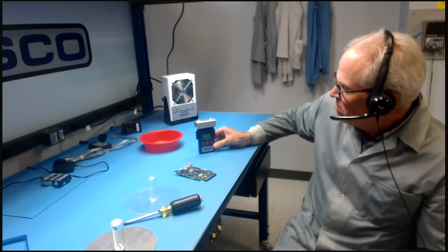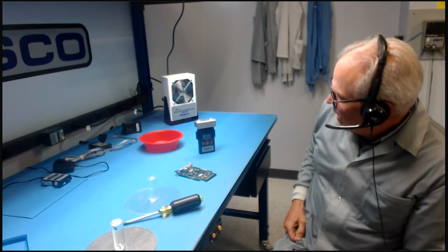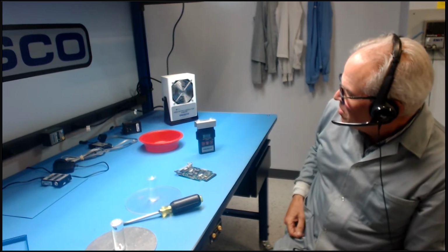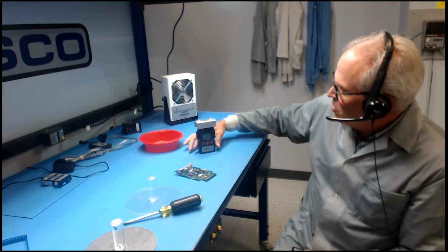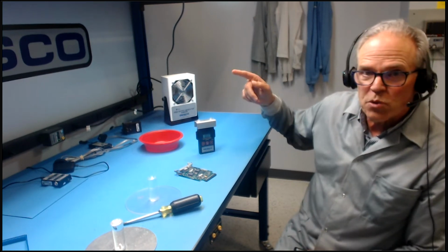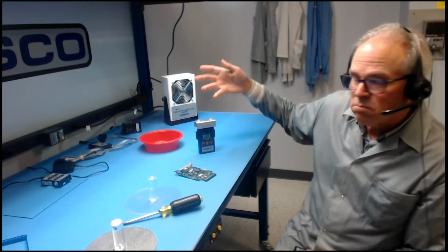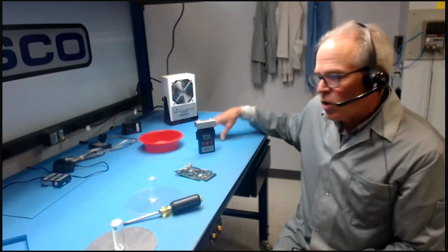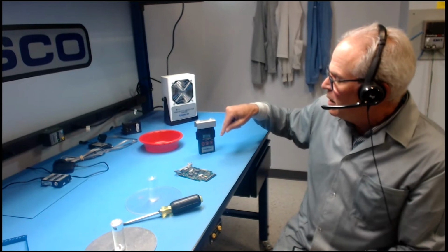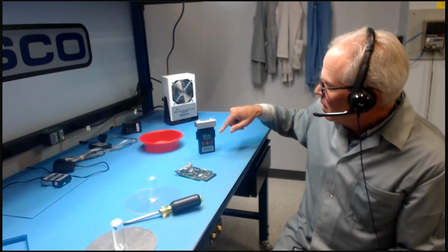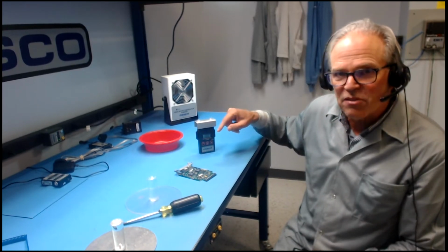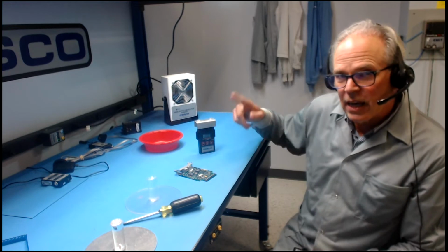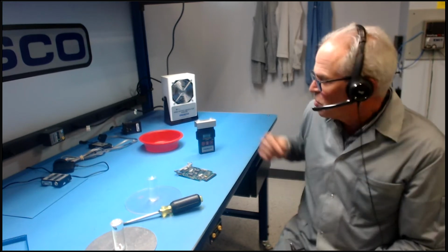put it underneath. And that took about 3 seconds. And now it's at 0. If this ionizer was out of balance, it would show some number, 10, 20, 30, whatever it would be. So you can do the decay test and the offset voltage test at the same time. And again, we're looking for 35 volts.